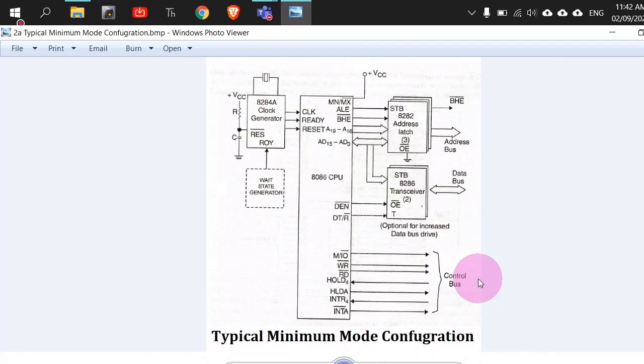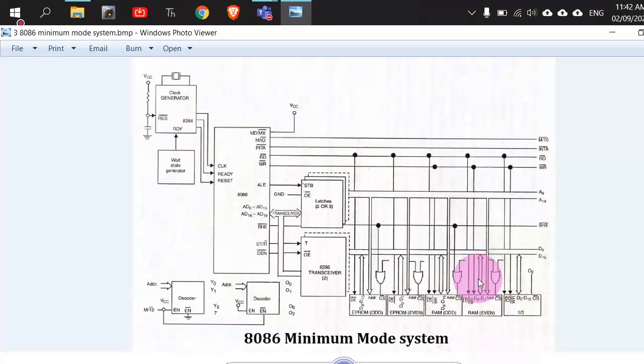But before that, let us see a general introduction to the timing diagrams of minimum mode, right? For that, let us first note a few points. We will develop some theoretical points before that, which will help us understand these timing diagrams better. Although we have studied timing diagrams for 8085 already, on similar lines the operations will happen here. So for a typical instruction in 8086, at least 4 timing cycles will be consumed. 4 T states will be consumed. T1,